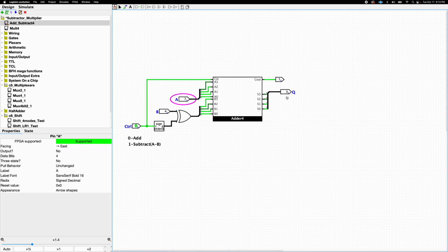Also, it should be noted that our range for our output, because it's also signed binary and only 4 bits, again, can only give us an output of -8 to +7. So say if we try to do 7 plus 4 here, which is going to be way over the range, that's going to be 11. This output is obviously not 11. This is -5. So as you can see, this has some drawbacks. We could spend some time trying to figure out how this makes sense to represent +11, but right now I have no idea how that works.